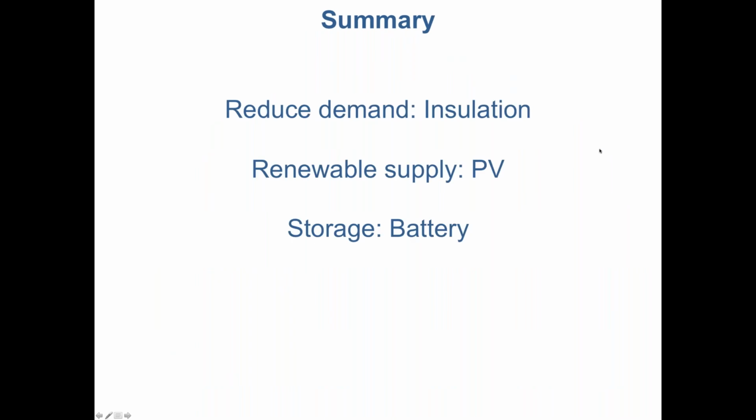So I'd like to just summarize those surveys, the whole house retrofit surveys. So we can reduce demand with the insulation, the draft stripping, etc. So we can reduce the heating demand, and that reduces the household energy costs quite a bit. I guess the biggest energy cost reductions are due to the renewable energy supply, because electricity costs are quite high. And so the PV, although it costs a lot, it does save quite a bit of energy.